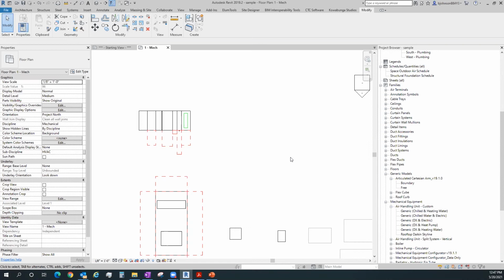Placeholder family works very well for that. If you go a little bit deeper with placeholder families and you generate your shared parameters, but you don't need anything higher LOD than say 100, 200, or 300, depending on the block that you built. You can usually get away with using a placeholder if the only thing that's available to you is super detailed and it blows up your model, or there's nothing available to you whatsoever.